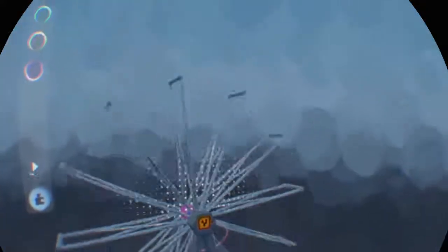Okay, so now we're all done in here. We're going to save this as is because I wanted to get that. As a motor bolt, it wasn't working properly. It was rocking back and forth. And that seems to be what motor bolts do by default, and I don't know why. Sometimes, but you want it to spin. So rotators work great for this purpose.